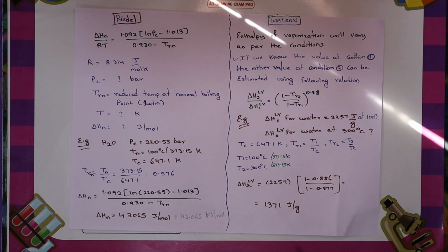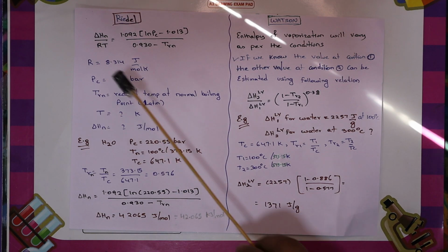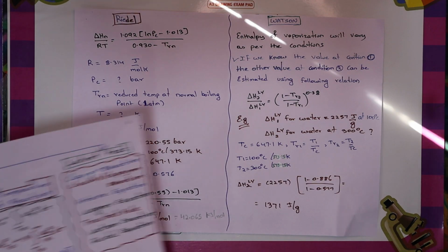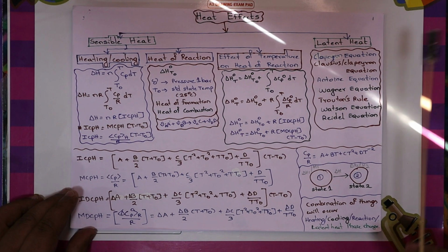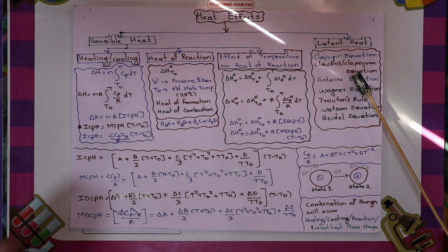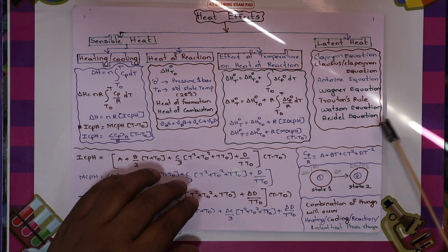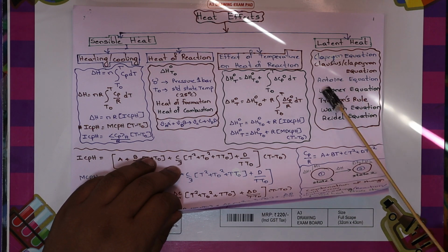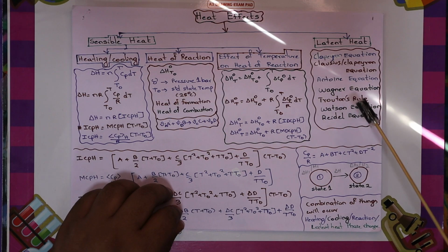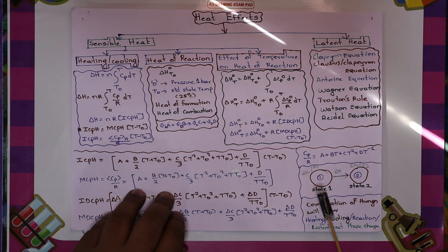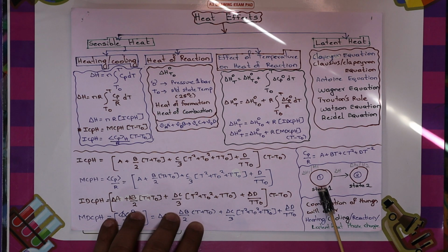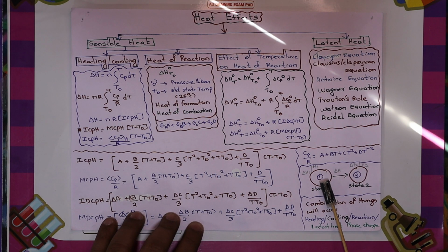So this is how these enthalpy calculations work, because if you remember, our agenda is to get some information about the latent heat. Riedel, Watson, Trouton, Clausius-Clapeyron, these are the different kinds of equations from which you can get the enthalpy of vaporization data. Why is it important? Because we are trying to find changes in enthalpy, taking the system from state 1 to state 2.